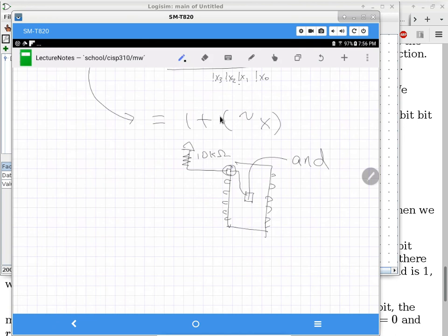So this way, you don't need a lot of current to put a voltage on this pin, because it's what we call a high impedance pin. If it's an input pin, it's typically high impedance. What is impedance? It's kind of like resistance, but applied to AC circuits, right? So this circuit has a high impedance input, which means it needs a very small, really tiny current to pull the voltage of this pin to whatever the supply voltage is.